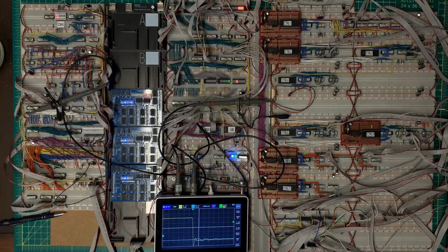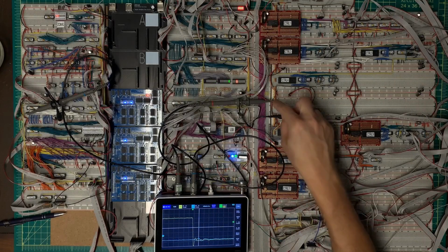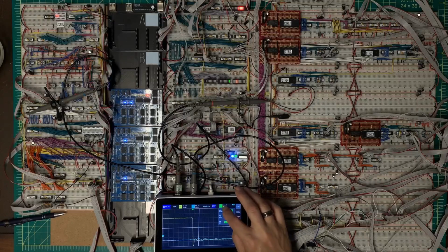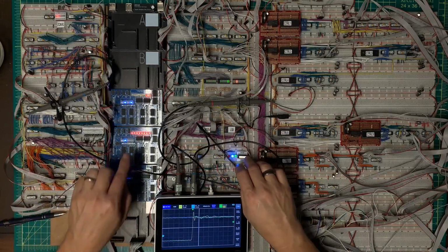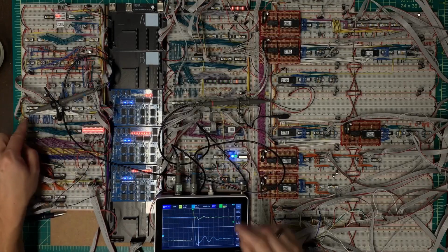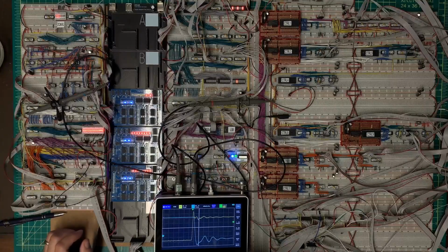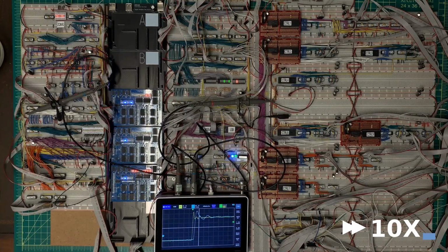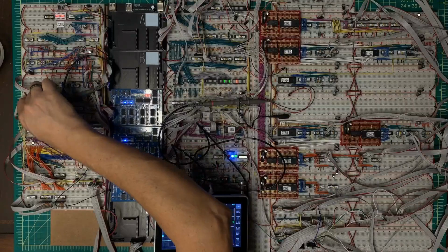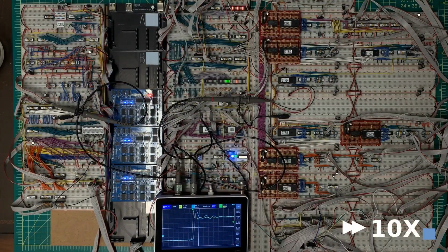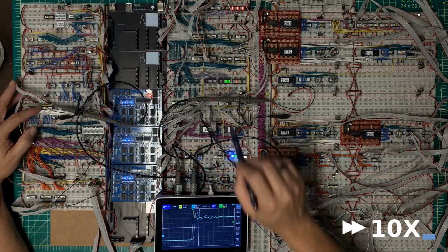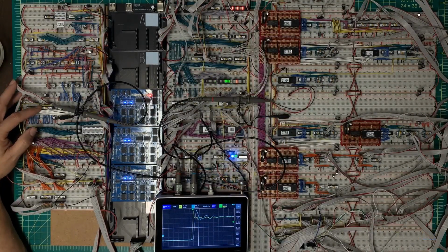Okay, that should be A. So that's low. When that falls low, I need that on the rising edge. That's not the signal I wanted to measure though. It's the one after the second add, so I'm loading the registers for that. That looks reasonably good. Now let's take a look at when that latch happens. So that's latching way early.